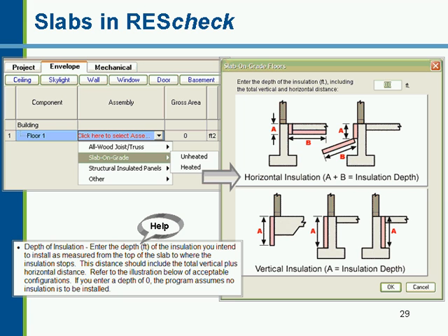And lastly, the slabs. Again, you get another screen that comes up, and it wants to know, well, how are you insulating your slab, and what is the insulation in feet? Slab is the only input in the software that is in linear feet. So you're only calculating up the linear exposed edge of the slab that's applicable to your thermal building envelope of the project.